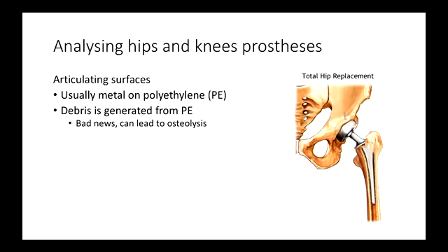Okay, so that's all talking about the bending, stiffness and strength. But what about the articulating surfaces? It's kind of different. That's all about contact stress. So the more contact stress, the more material that can get abraded off. So we need to analyse what is the contact stress. Because, as I was saying, it can get abraded off. Anything that gets abraded off leads to more stress, and then those little particles can cause infection, osteolysis inside the joint.